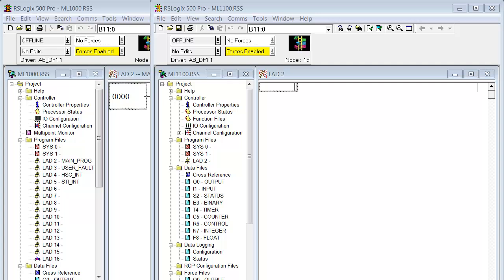It also, for the 1500, the function files would do data access terminal, or DAT type information. There's also trim pot information, memory module information, base hardware information, communication status file channel 0, communication status file channel 1, communication status file channel 2. That's the 1400 only. And then Ethernet communication status file for the 1100, Ethernet communication status file for the Micrologix 1400. For the 1100 it's called ES, and for the 1400 it's ES1.